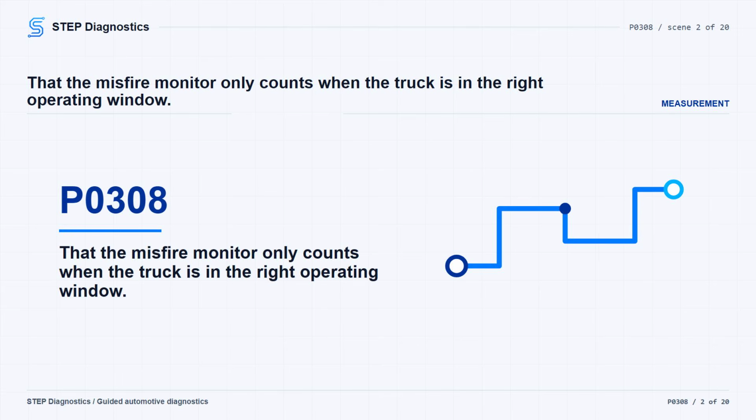The misfire monitor runs only when the right gates are met: fuel level above 12%, battery voltage above 9 volts, ambient temperature above -23 degrees C (-9.4 degrees F), coolant temperature at engine start above -7 degrees C (19.4 degrees F), or if the start temperature is below threshold, when engine temperature reaches 21 degrees C (69.8 degrees F), engine speed is between approximately 400 RPM and 6,200 RPM, and the monitor is disabled during a decel fuel shutoff event.